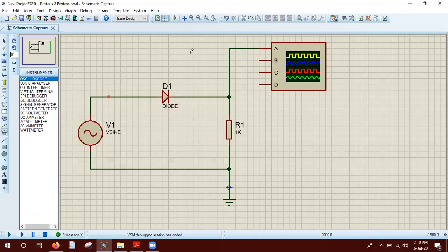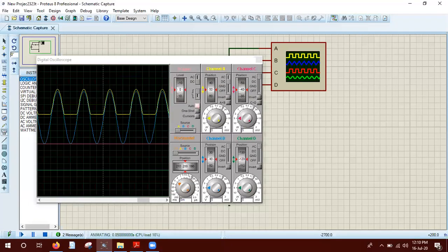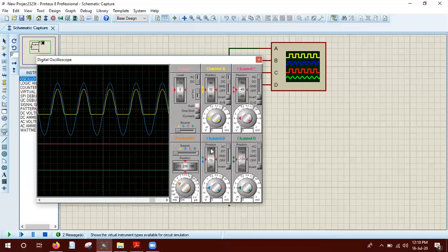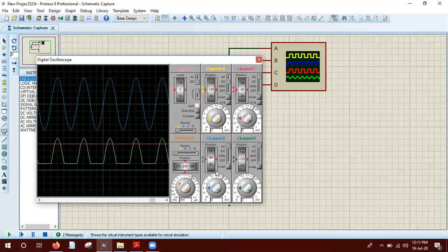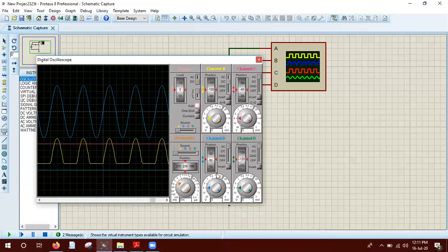Okay, it will help us much more if we see the input and output together. Let me connect the input voltage in the B channel, and let me run the signal one more time. You see that channel B is connected together. So this is the input, my students, and this is the output. In the input, you can see that during the positive cycle, we get the output positive, but during the negative cycle, we are getting 0. Am I clear here? Yes, sir.